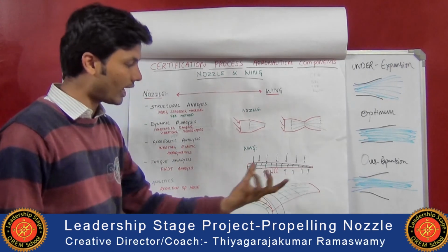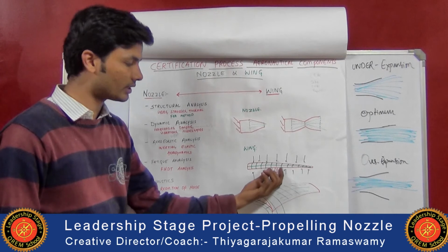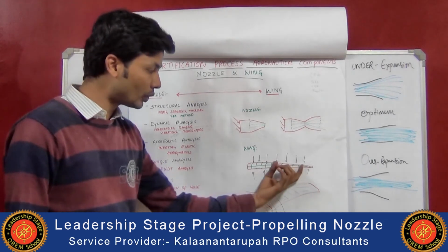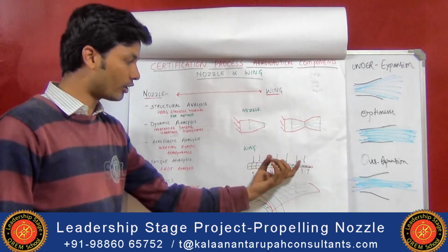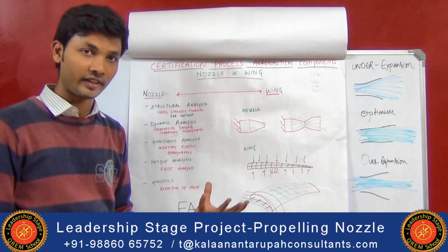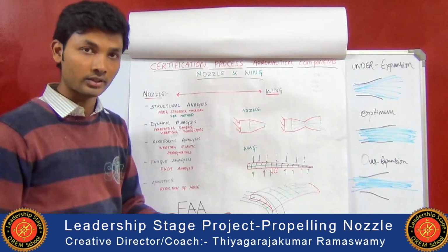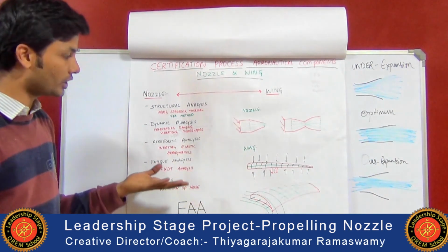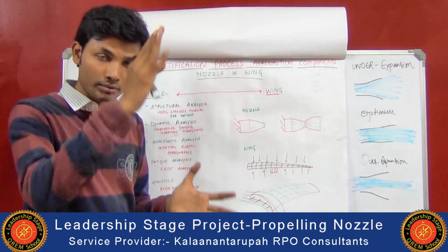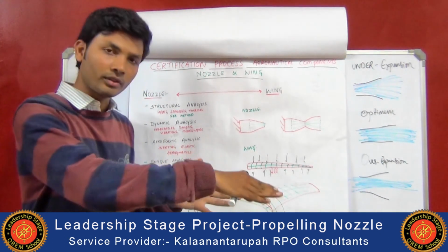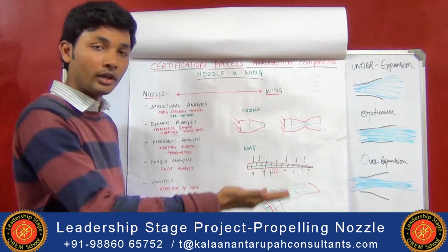The loads we apply on the wing are the engine weight, the fuel lines and the fuel usage which will be passing through inside the wings, and for the aerofoil frame and the ribs, the self weight of the wing, and also the aerodynamics. Everything will come into consideration, and because of the engine there will be vibrations on the wings as well, and the mode shapes of the wings because of the wind and the aerodynamics.